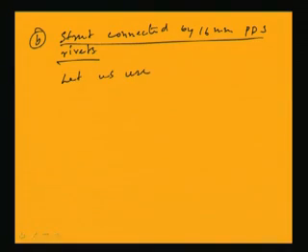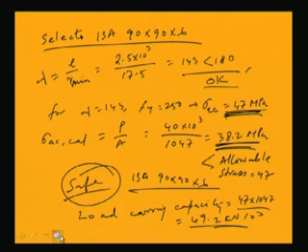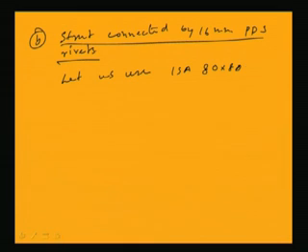So, now let us first use the previous section, ISA 80 by 80 by 6, which was unsafe for the earlier case. Let us use ISA 80 by 80 by 6 section, which was unsafe in the previous connection, okay. Now, we will see whether this is safe or not. If it is not safe, we can go for the next section.